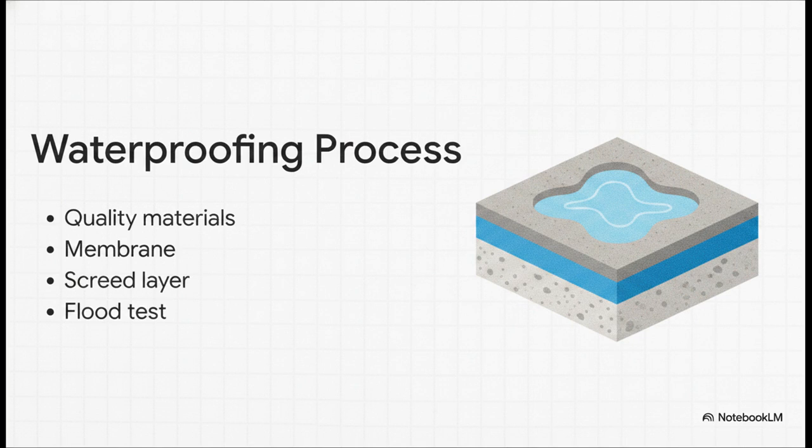Look, waterproofing is essentially a race against water, and you have to win. The process demands high-quality materials right out of the gate. It requires meticulous membrane application across the entire sunken area, followed immediately by laying a protective screed layer so that membrane doesn't get punctured by someone's boot during the rest of the build.